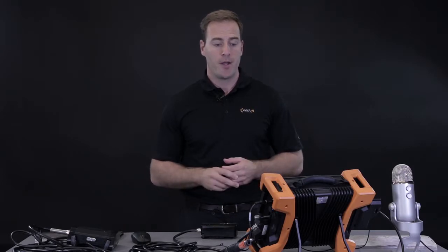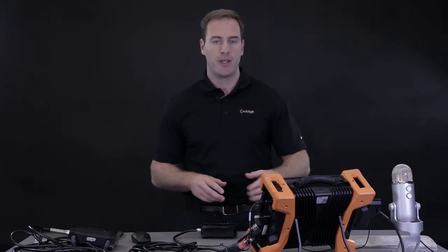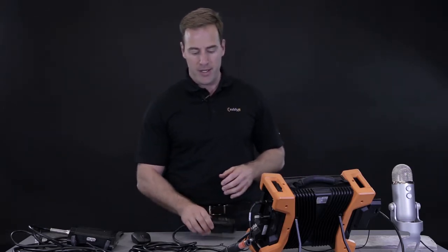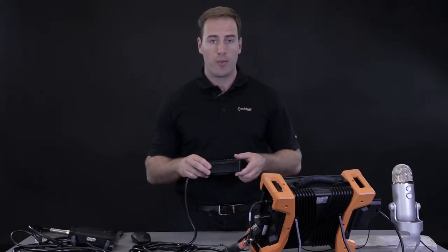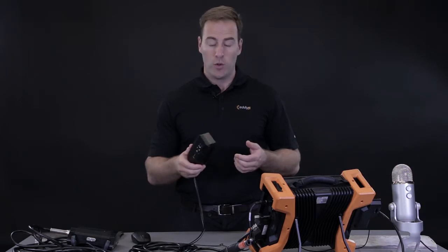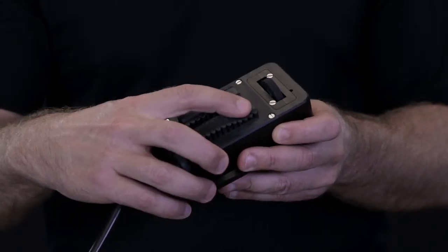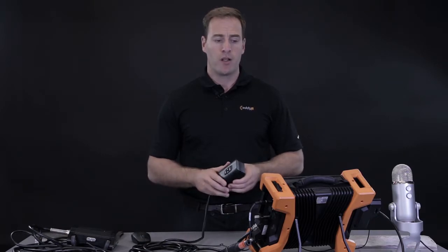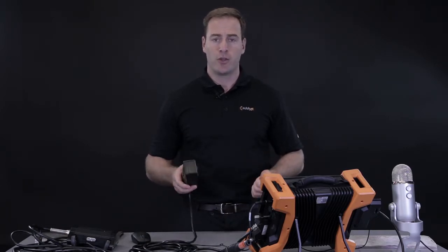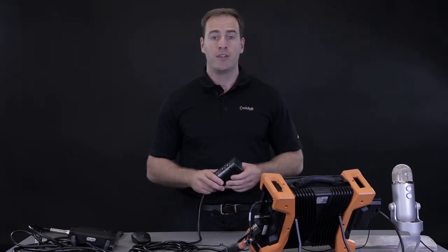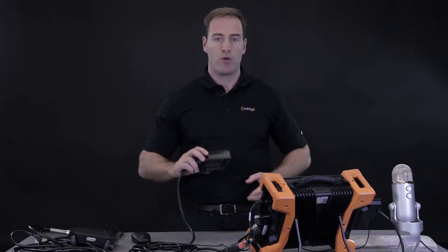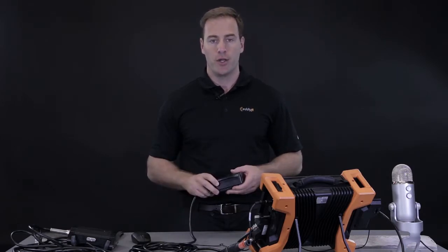So basically today I'm gonna demo two of our Sharck probes with the portable instrument here, the Reddy instrument. Basically, the two probes that I want to demo will be these probes. The first probe is the Sharck probe, basically for a butt weld inspection. This probe has a spring-loaded element, so that makes it so the probe can fit any kind of butt weld. If we talk about pipelines, this probe could inspect the girth weld, the longitudinal weld, and even the spiral weld. And we could run with this same probe both circumferential or longitudinal scans along the pipe.